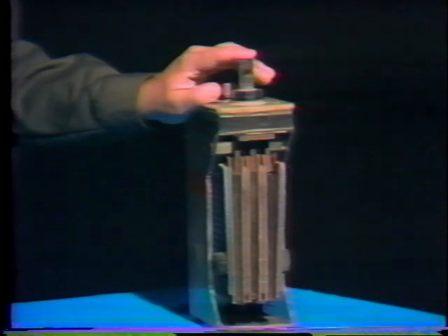Eventually, it drops below a useful level, as we'll see in a little while. As a lead-acid cell discharges, the chemical action that takes place is just the reverse of what we saw while the cell was being charged. During discharge, the sponge lead electrode and the lead peroxide electrode both change back into lead sulfate, and the electrolyte changes from mostly sulfuric acid to mostly water. Discharging the cell puts us back where we started from.